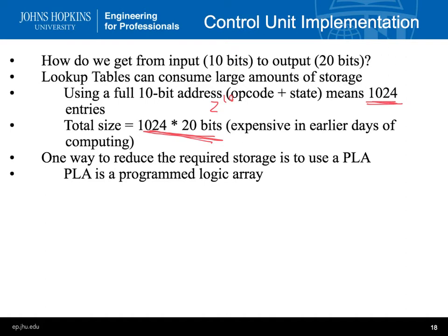Which in the earlier days of computing cost a lot. But we don't really have 1024 possible inputs, it's really a lot smaller than that. Sets of where we are now state and opcodes. There's not that many possibilities really. So we're going to show how we can store it in a programmable logic array that's a lot smaller than 1024 times 20.